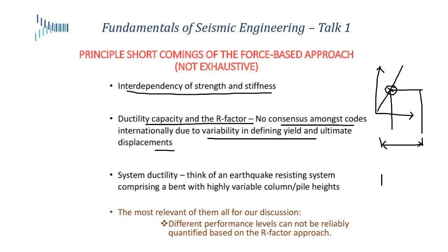Okay, so we saw that the R is equal to the ductility value. And if you look at some of the codes, or all of the codes for different systems, they'll give you the force reduction factors, which basically tell you how much to reduce the force level from the elastic level to the design level for different systems. And it's all dependent on how much ductility we think we have in a given system.